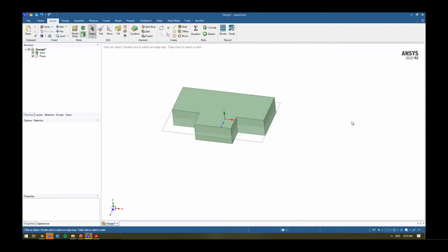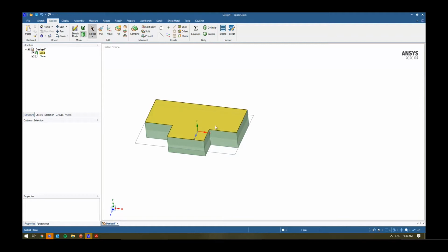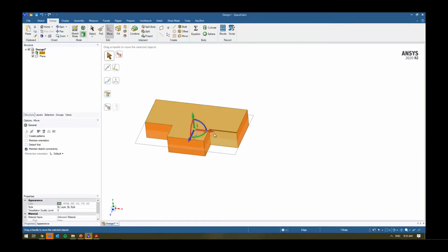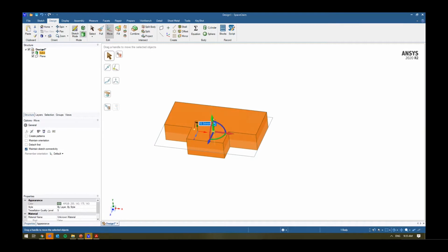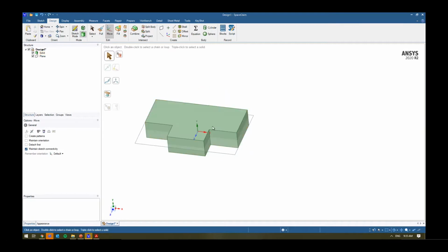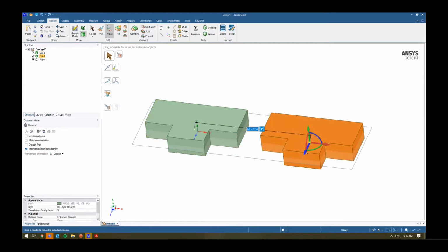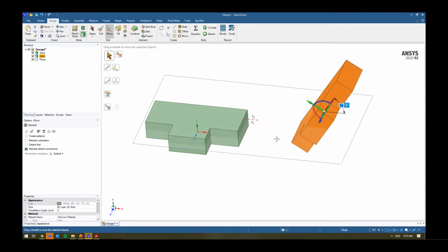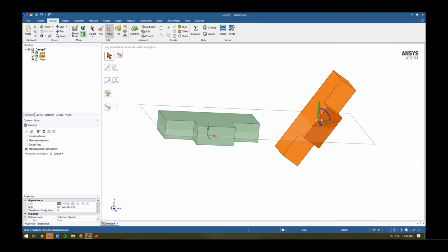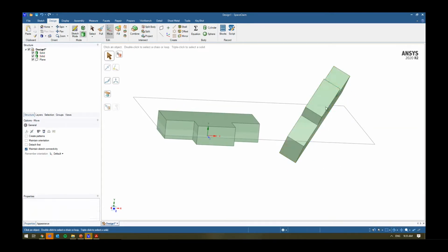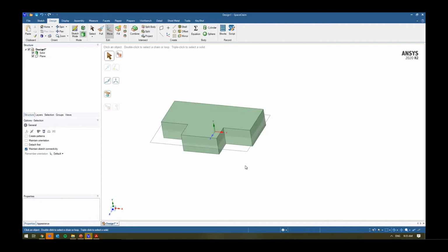How to copy solid bodies, yeah, so that was one of the things I'll do later on as well. But what you can do, you can select it, and you can use the move function here to move something around, right? XYZ directions. If you select the whole body though and hit Control on your keyboard, you can create a copy of something as well, right? So you can then start to move it around however you need to, right? So that's how you can do that.